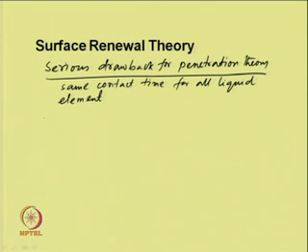So, it is highly or more likely, more probable that there is a distribution of the ages at the gas liquid interface. Due to turbulent flow conditions, the eddies may sweep away the interfacial elements of fluid. So, they will leave the surface very quickly, and some element may stay at the surface for longer time.